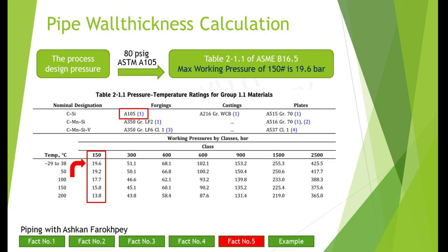The first reason is when performing wall thickness calculation, using too small design pressures would give us thicknesses that make the pipe vulnerable to construction impacts and pressures. This makes the welding also too difficult.